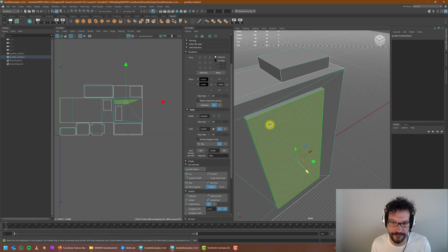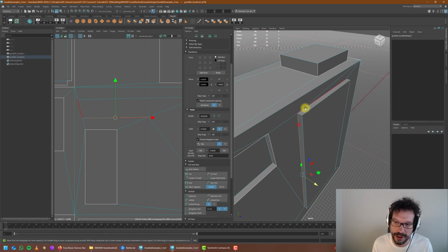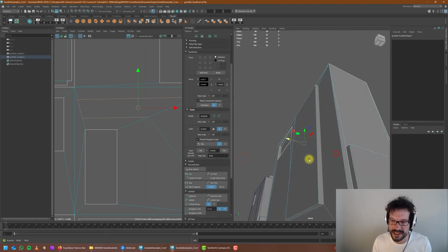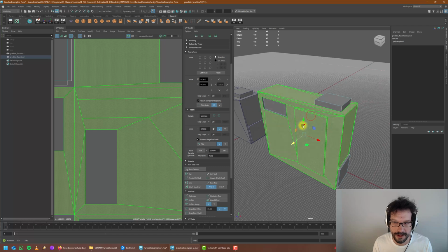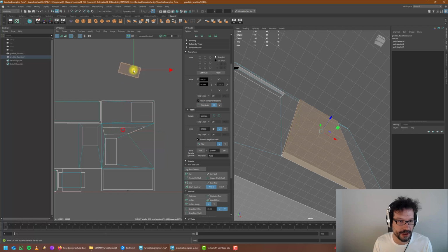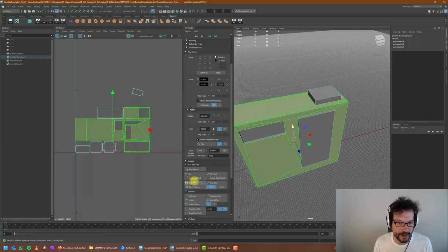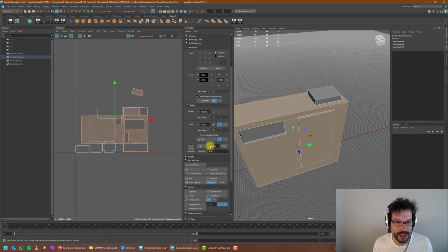For example, we have to first grab these pieces and break them apart. We have to cut all of these edges like we did with the other ones. Cut. Let's grab this UV shell. We'll make sure everything is cut first. Oh, this one was missing. Okay, let's go to the UV shell. Let's grab this one, hit unfold. There you go. Now this piece has changed. The rest of the pieces haven't changed at all, but this one we elongated and modified, so we're gonna unfold it again.